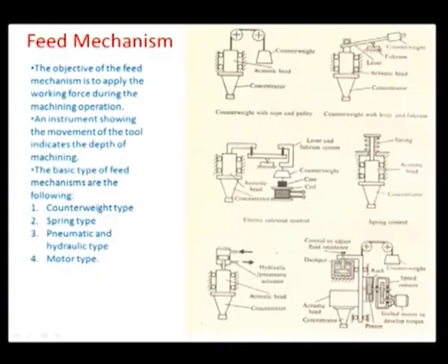The other important aspect is the feed mechanism of ultrasonic machines. So as I already told you, the feed mechanism is really not the mechanism which generates the frequency of motion. The frequency of cutting is generated by the acoustic head, as I told before. The feed mechanism is just to position suitably the acoustic head, holding the tool with respect to the workpiece, so that you can actually utilize that frequency of the acoustic head very close to the workpiece surface, so that you can have maximum cutting action.